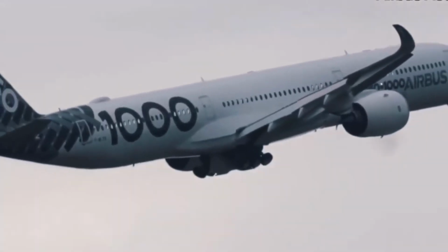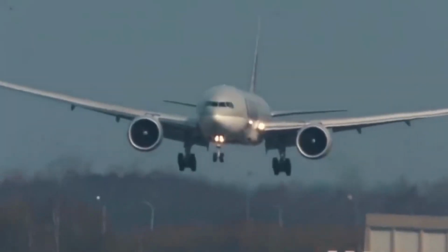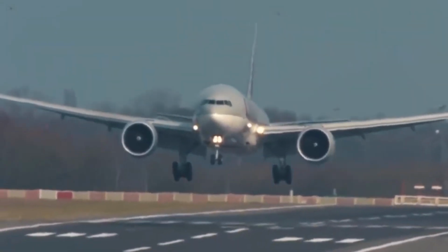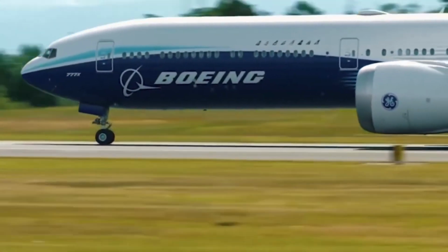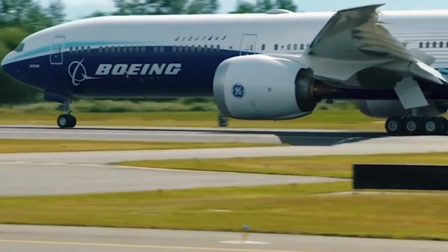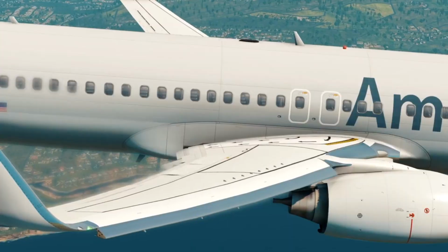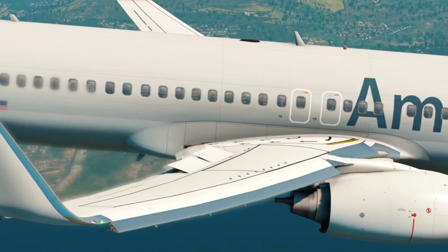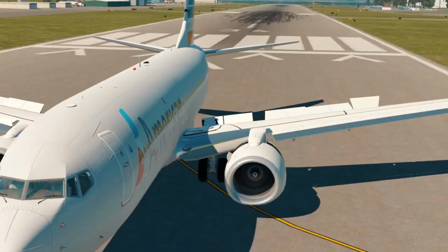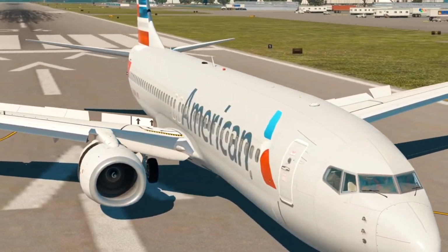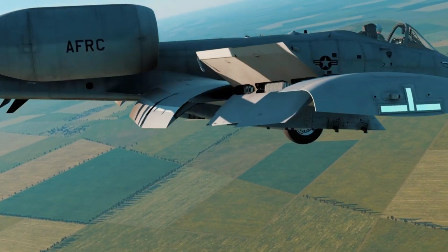The movement of flight controls is converted to electronic signals transmitted by wires, and flight control computers determine how to move the actuators at each control surface to provide the expected response. Flight control systems have helped reduce pilots' workload, minimize aircraft weight, improve handling qualities, and are reliable.